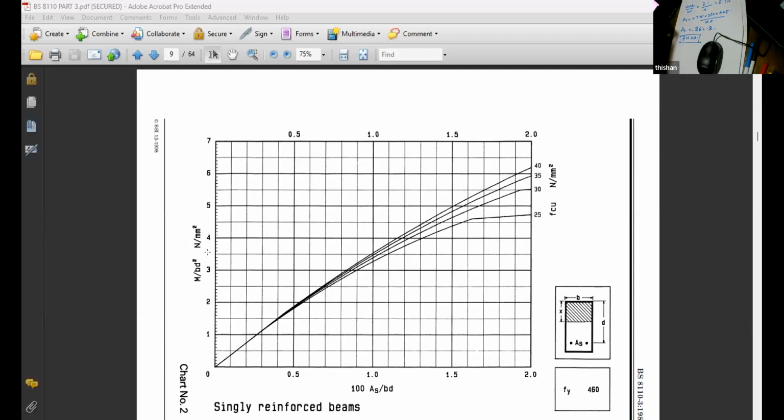If you need, say, 200 millimeter square steel, then you have to provide it. So select the correct welded mesh. Welded mesh, no special rule. You calculate the reinforcement, and use the same area from the welded mesh. That's all.